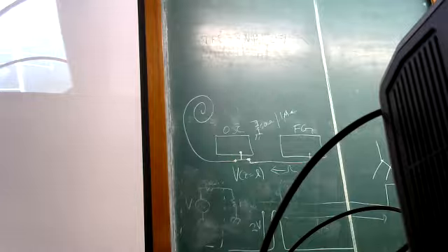So in the oscilloscope, maybe we would see 1 volt till some time t naught, and after that it will directly become 2 volt here. You will see 1 volt for some time. Why 1 volt? I'm thinking that the characteristic impedance of the long wire is 50 ohms. So it will be similar to the case that we saw last time.